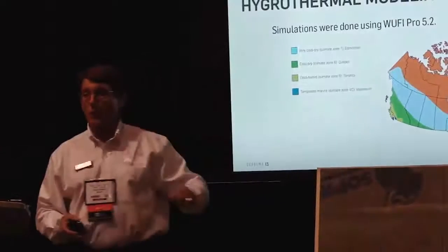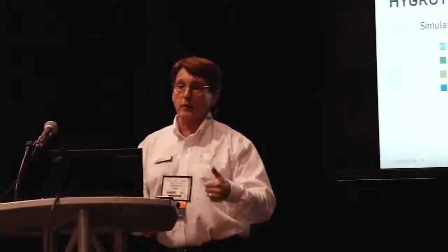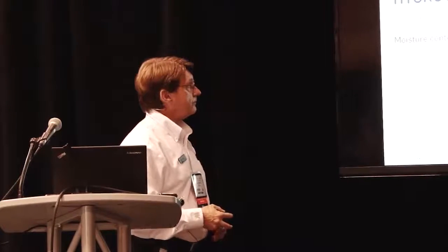Important to know, though, when you do a dew point calculation or these WUFI calculations, there's a known variable: no air leakage. So all of this is about vapor permeance on the premise that there's no air pressure pushing moisture through the wall. This is simply a measurement of vapor diffusion with no air leakage.